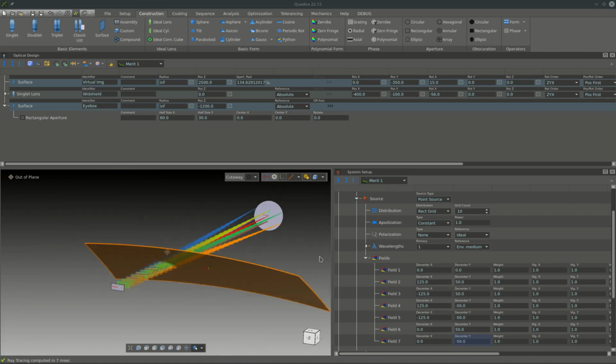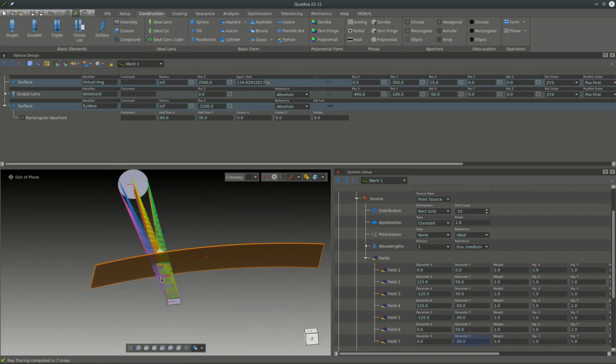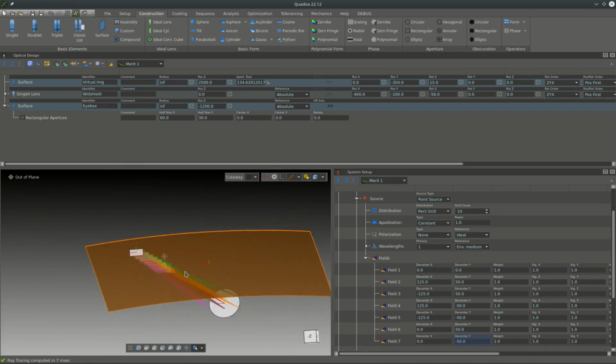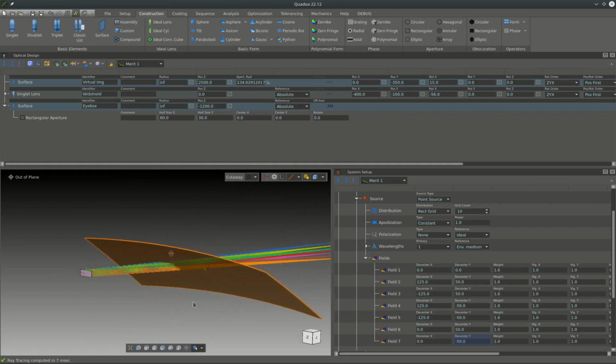Now, since everything here is off axis and also the rays get reflected at an angle from this freeform windshield, we will add a dummy surface down here and we will align the surface to the chief ray, and this will be our reference ray for the positioning of all the head-up display optics.